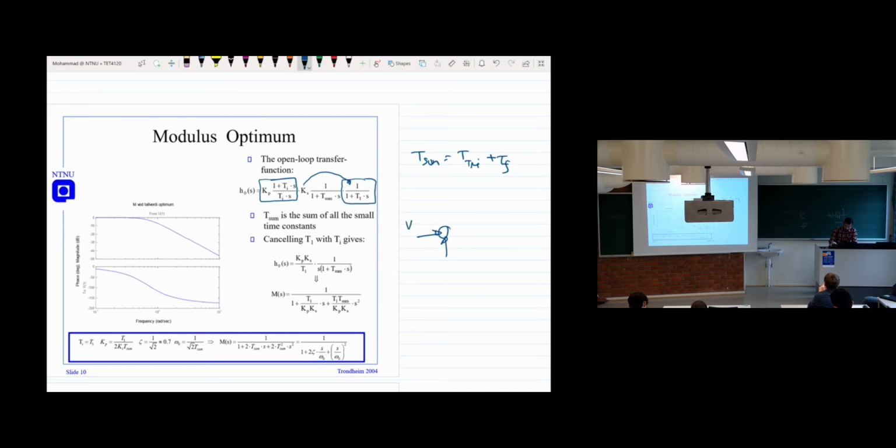If it's a machine, then you can represent it something like this. We have the controllable voltage generated in the machine, and then 1 over SL plus R. Here L could be the armature inductance, and R the armature resistance.